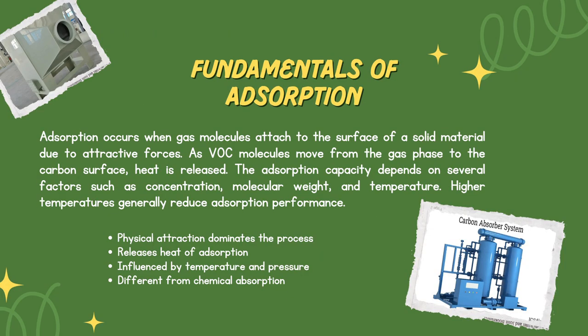For the fundamentals, adsorption occurs when gas molecules attach to the surface of a solid material due to attractive force. As VOC molecules move from the gas phase to the carbon surface, heat is released. The adsorption capacity depends on several factors such as concentration, molecular weight, and temperature. Higher temperature generally reduces adsorption performance.